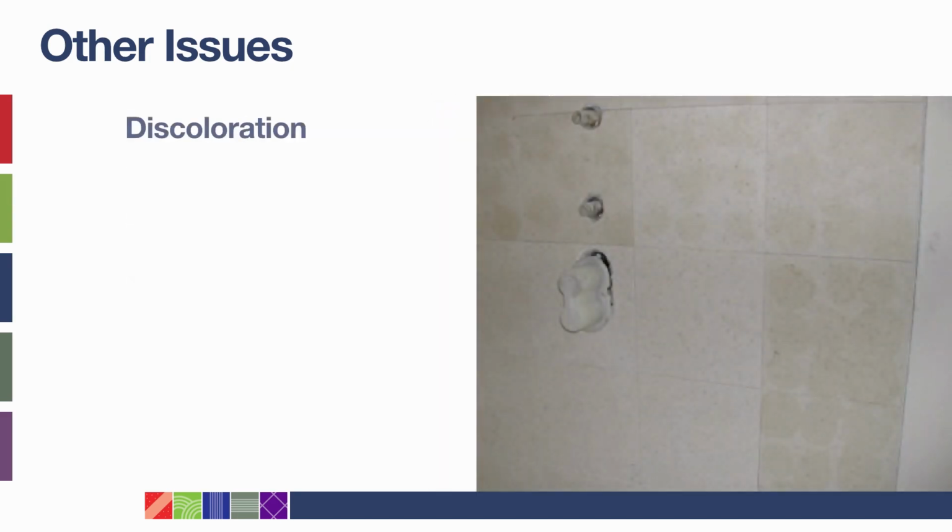Because some stone is porous, it stains very easily. Its pores absorb materials like a sponge. Taking special precautions to avoid installation pitfalls will help prevent staining. Earlier, we discussed the importance of achieving 100% coverage when installing stone tile. Doing so will help to avoid unsightly staining and discoloration,